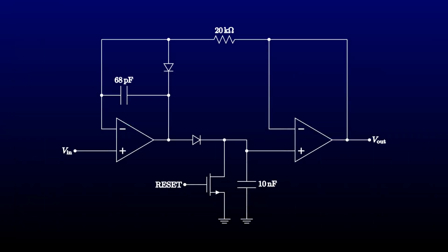We were working with a circuit like this. When the voltage rises to a new peak, the capacitor should match that voltage, meaning that it will carry a proportional charge. When the voltage drops below the peak, the diode cuts off, and the capacitor should just sit there, charged, holding the voltage. But that's not what we're seeing.